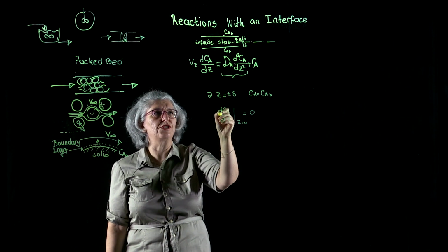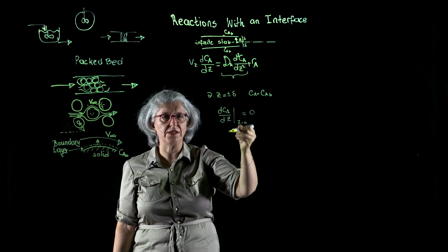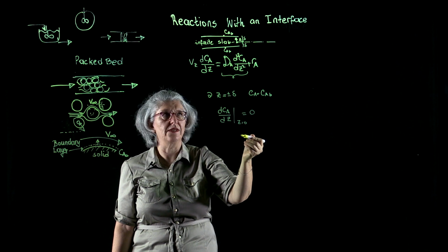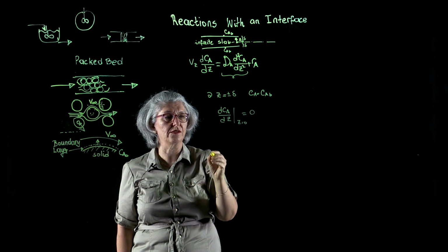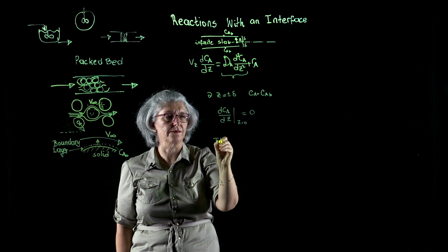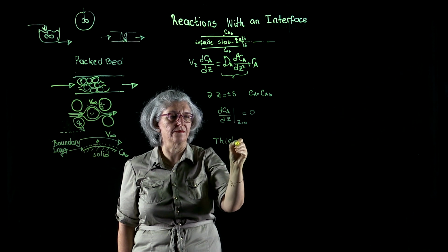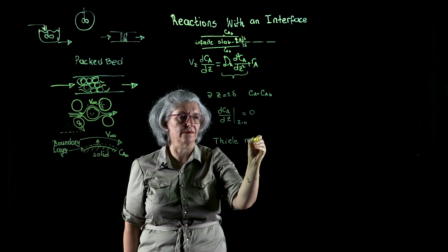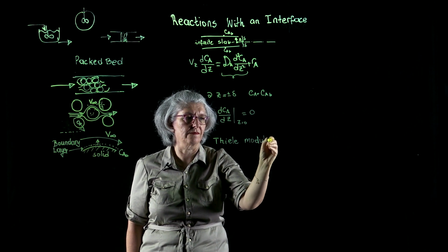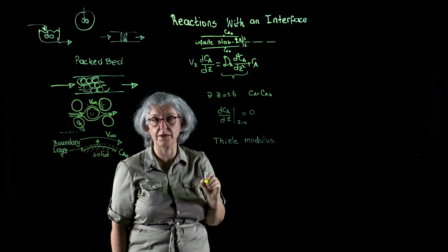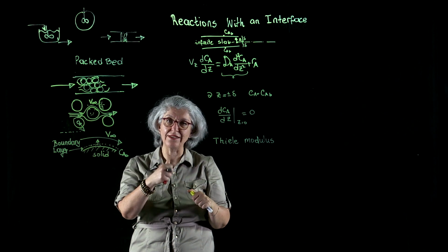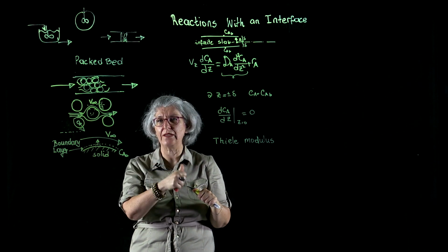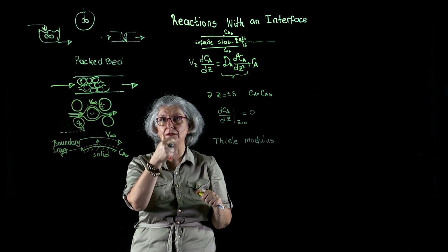Now, solution of this differential equation is going to bring us a parameter which is called the Thiele modulus, or Thiele parameter. This Thiele modulus is going to scale the rate of reaction with respect to the rate of diffusion.